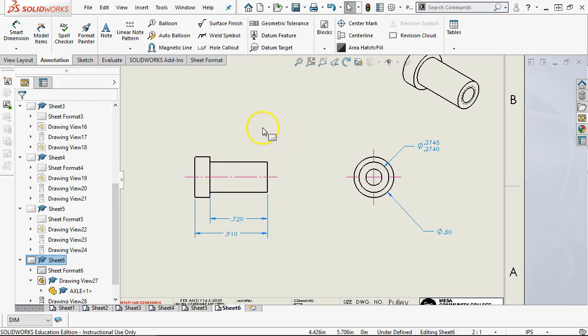And so of the mix, I don't really want to use circularity here, because if I cut this into individual segments, that whole virtual component of the center line can arc or move around, but this can still be circular and within tolerance. When we look at the 0.5 tolerance, well, that really puts the crimp on being able to move the center line, our virtual center line. But within our tolerance positioning between these 2, I really don't have anything that's that critical. When it comes down to it, the tapped hole doesn't necessarily have to be on center, it just has to contain.